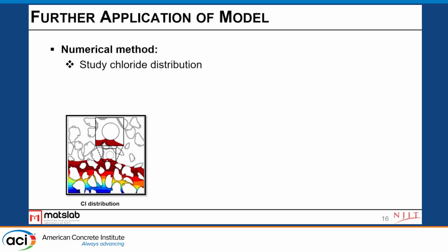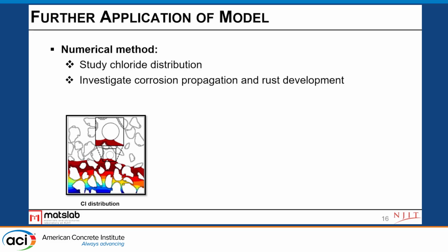And then we have a model that is set up where we've connected Diana with COMSOL so that we can input the mechanical properties. It will put it under some stress. It'll go into COMSOL. It'll measure how much chloride is moving through on different time steps. And then at the end of the day, we get both mechanical damage and chloride ingress into our system.